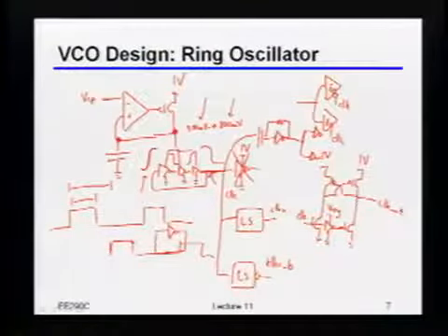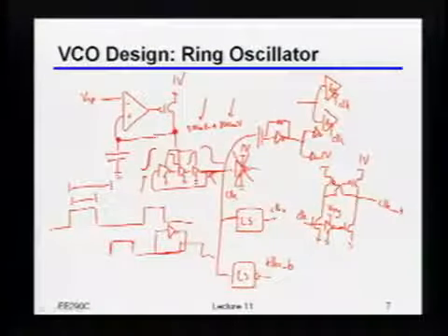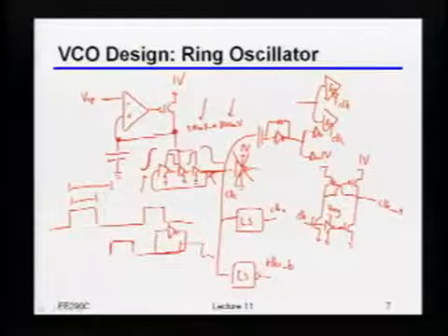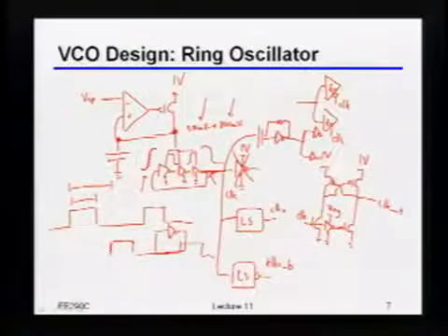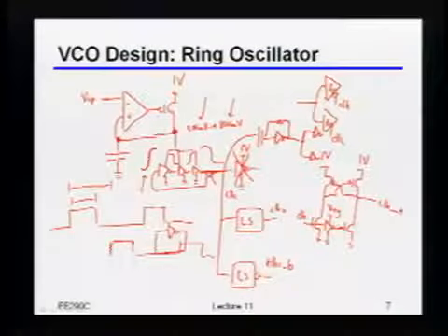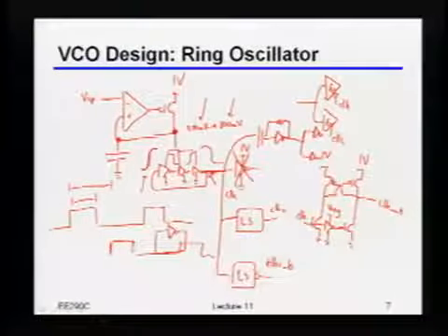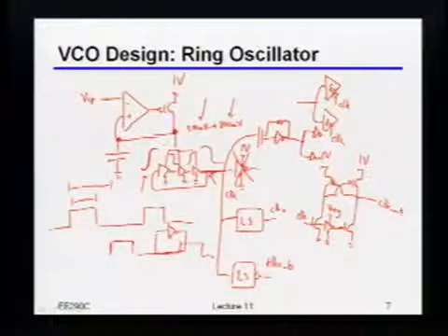Yeah. Well, some of the VCOs I remember seeing in the past are fully differential. Okay, we're going to talk about that in 1 second. So there are VCOs that will give you what should be differential signals, but by the way, even there, they will mismatch, right? And again, we're going to draw that in just 1 second. But in general, there's no perfect way to do it. There's only getting it close enough. And then if you really, really care, you'll tend to end up building what's called a duty cycle corrector. So you'll actively try and correct those phases. Okay?